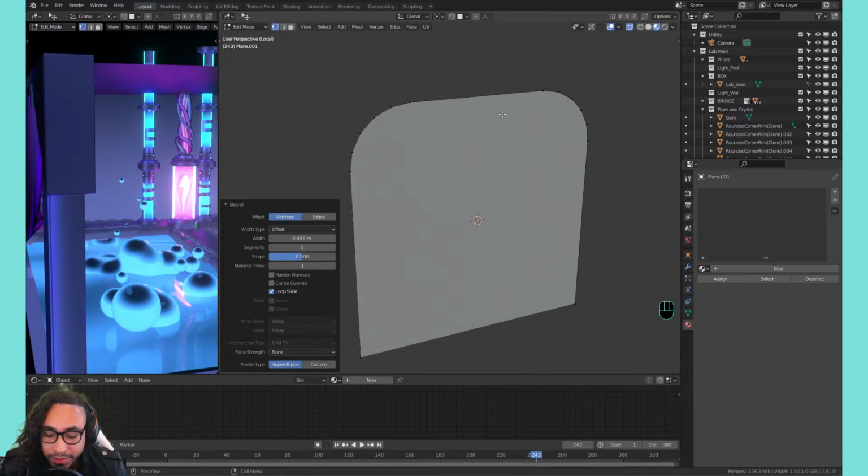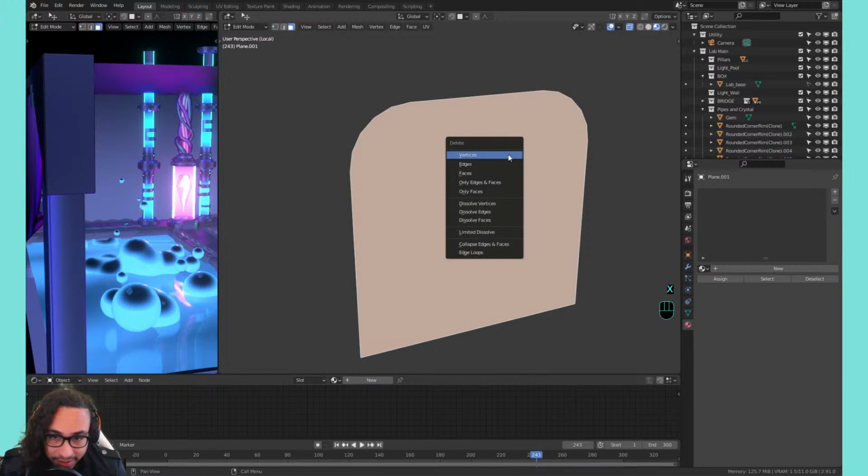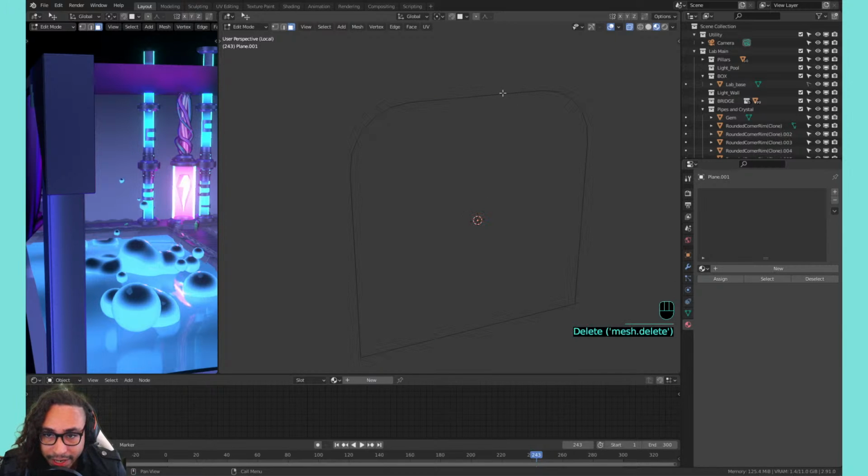And what I'm going to do is I'm going to go into face mode. So I press 3. I'm going to select this, hit X. And instead of doing face, I'm going to do only face. So it's going to leave the wire around it. All right. So now if you look at it, we just have the vertices and it has no face in the middle. I'm going to go into 2, right? Or what is this called? Edge select. Select this edge, and I am going to delete this edge. I don't need that edge. Okay, cool. So now I got the basis of what that rail looks like.